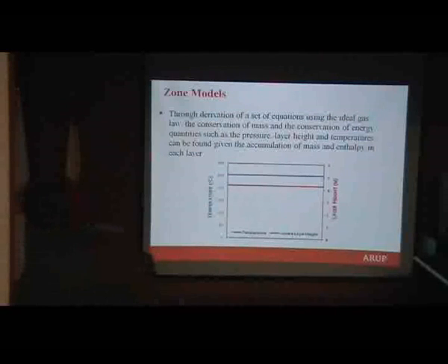So, through derivation of the equations of mass and energy, I can reach this conclusion, for example. So, achieved with a given natural ventilation, a certain layer height and a certain temperature. This can be achieved with software, or with a spreadsheet. I can mention, I don't know, CFAST, Ozone, FAST, and spreadsheets that you can do with just Excel and put your formulas on.